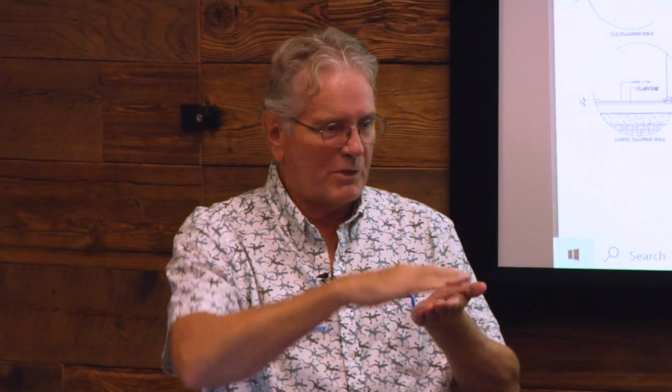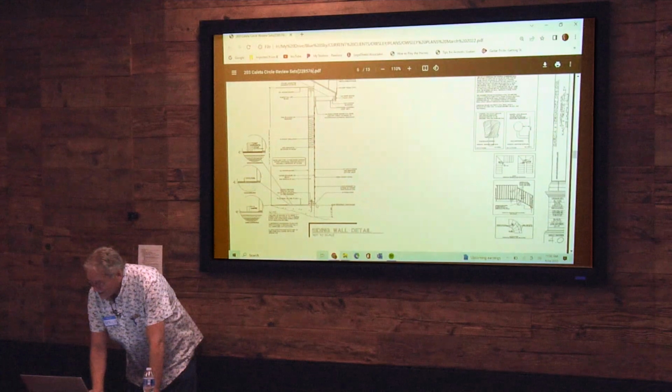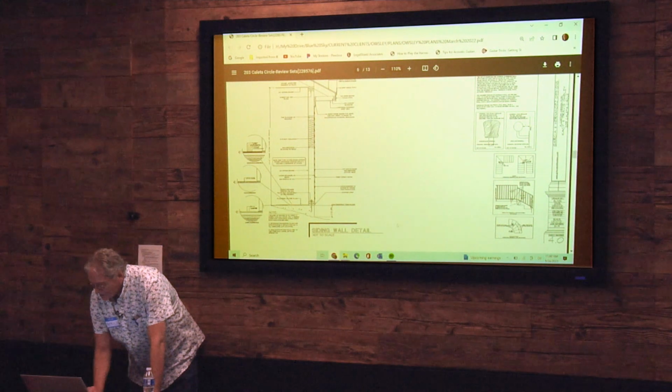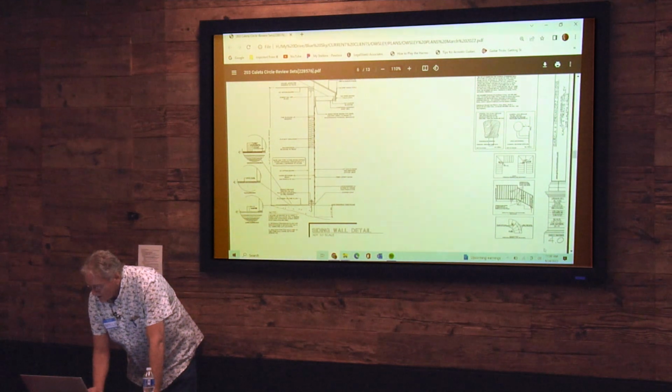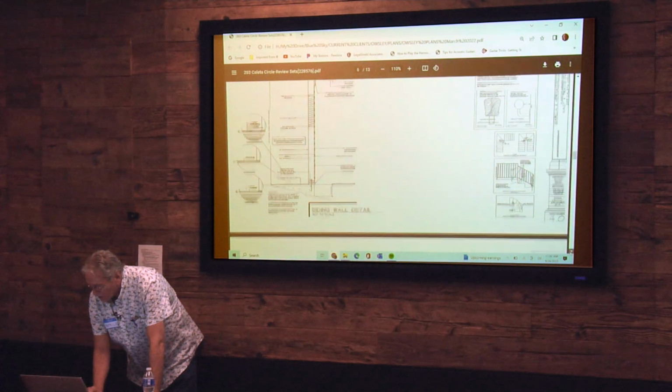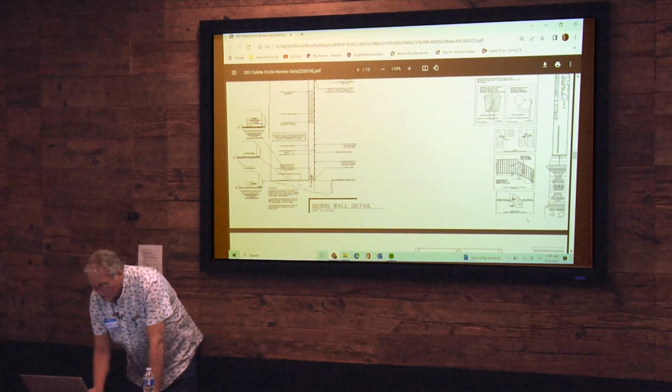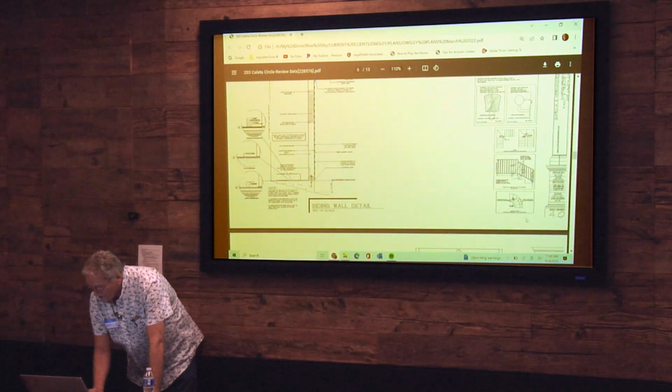You do that sometimes when you're going to have a screed wood floor, if you all know what those are. Typically, you either drop the floor or you double the plate. And you're getting the same 1.5 inch space, either way. It's a technical discussion for a whole other class. But again, this guy puts typical stuff like stair details. There are no, what do you call those, rounded stairs in the house.